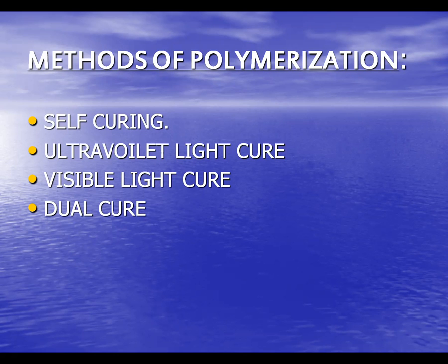So there is no need of an external heat source or ultraviolet light source. But the disadvantage of this is minimum working time. Right? When you start mixing these two composites, it starts curing. So the chemical reaction starts, and you can't control the working time. For proper molding and finishing of the composite, we need more working time.